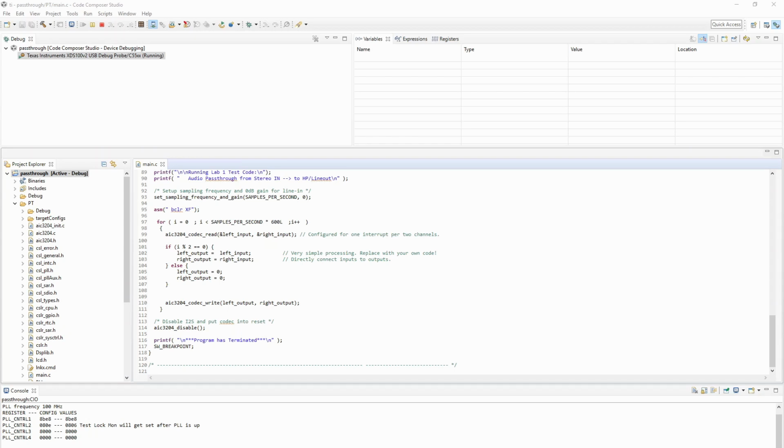I have some code up here on the screen right now that accomplishes exactly that. Decimation, of course, if you did your pre-lab, you'll know is what happens if you were to downsample your input by setting half of the samples to 0. So I have a little piece of C code here that you might be familiar with called the modulo operator. And this modulo operator is actually checking for the remainder.